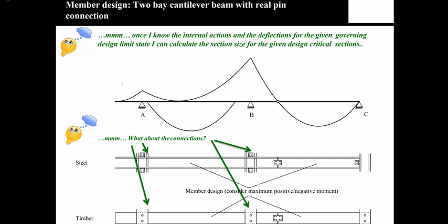So when it comes to normal structural design, what you would do is estimate all the dead loads, live loads, superimposed loads, and any other environmental loads, and you arrive at the bending moment envelopes, right? Once you arrive at the bending moment envelopes, which means the maximum moment demand at a particular section, it could be at a support or it could be at the midspan. Once you know those demands, as I said in my previous slide, you can easily size those members.